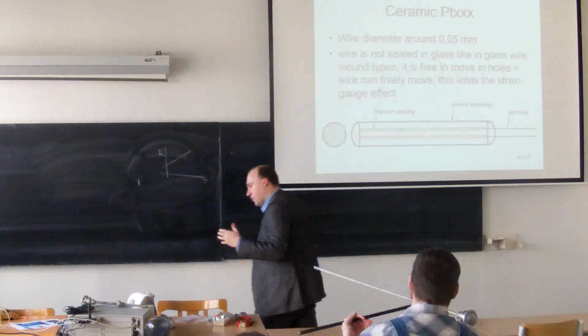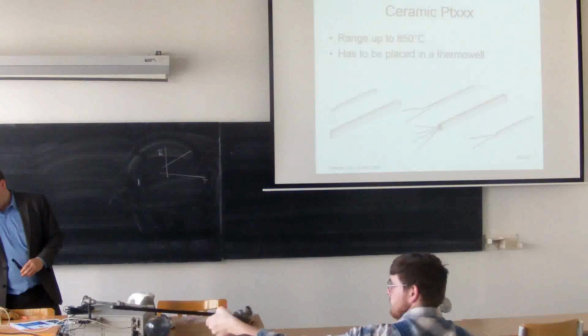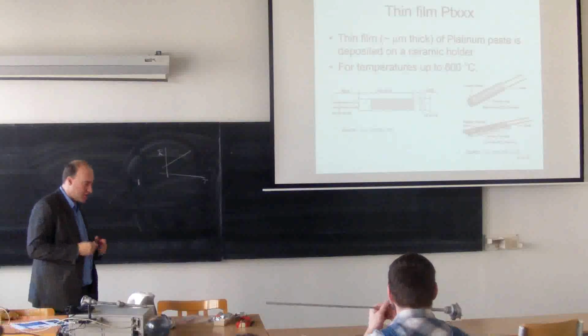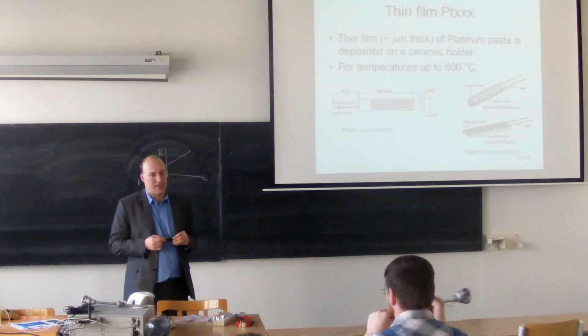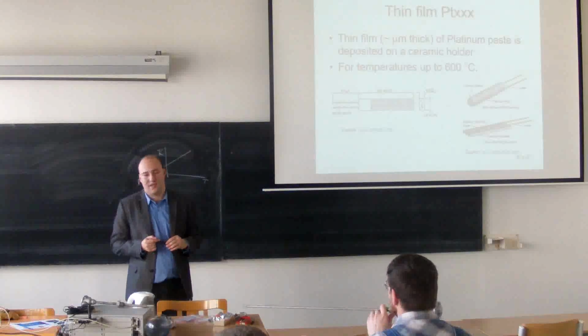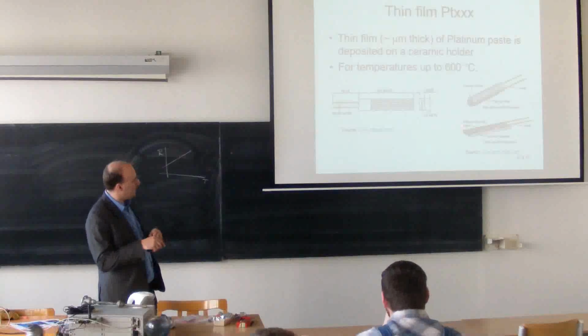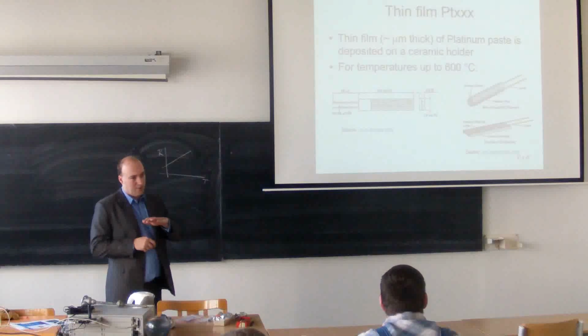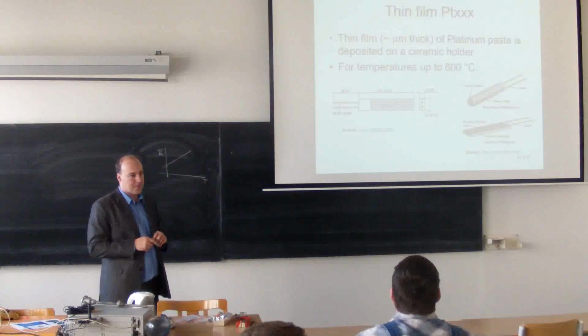So those are the two versions of the PT100. And the third version is a thin-film PT100. That's the one I showed you in the plastic bag. It looks like a thin film of platinum on a ceramic holder.